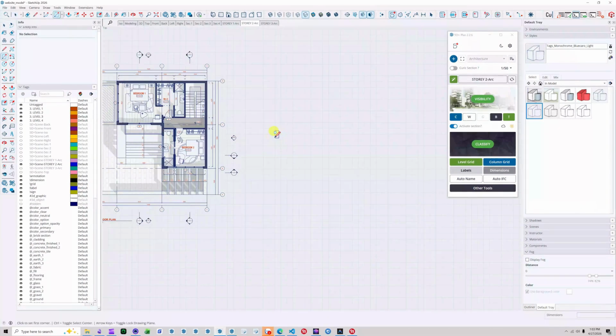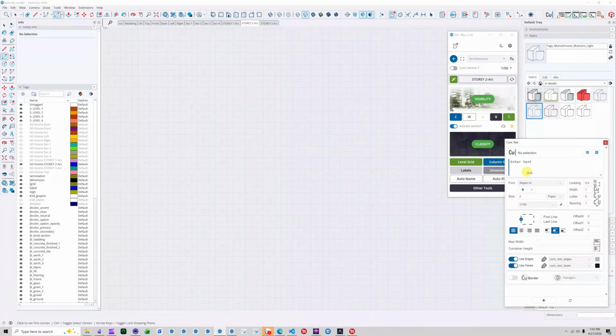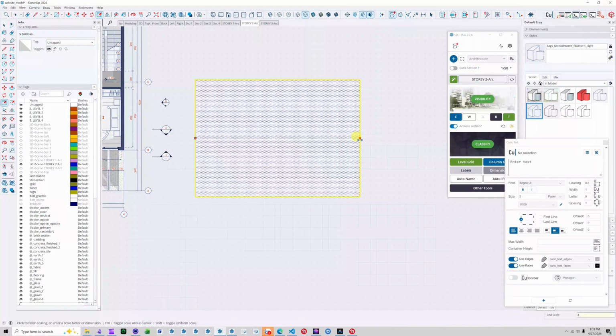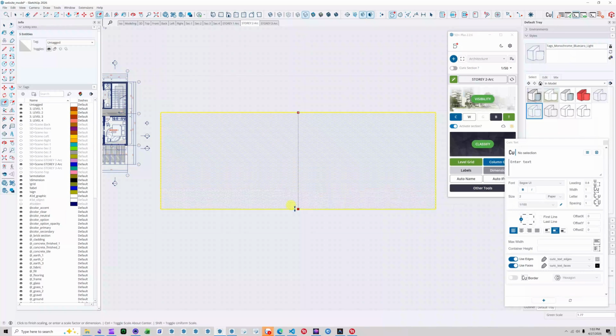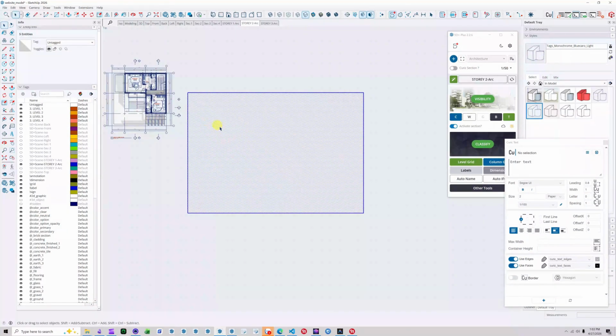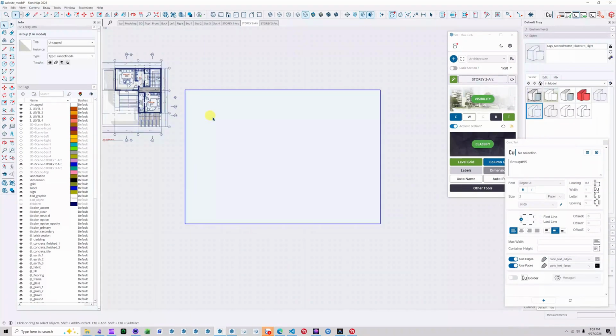Instead of drawing it to the exact scale of the paper size, which is the width and length, say 420 by 297, if you draw it to this scale and create the block, it'll end up being too small and could cause errors. So I'll scale it up by 100 times. I'll draw the paper frame like this, then I'll specify the two dimensions like this, setting them to 42,000 millimeters, for example. In this case, I'll also set it to 297 millimeters, then press enter, and now I've got a paper frame that's been scaled up by 100 times. It's a bit big, but that's all right.